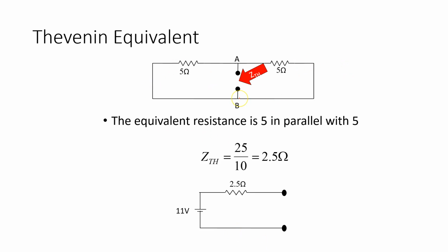If that is difficult for you to see, sometimes you look at it and you think that, well, these two look like they're in series. But remember, we're connecting from this point here. So if I take these 2 points A and B, and I draw a line like that, then I could say this resistor is connected from A on this side to B on this side. And this resistor is connected from A on this side also to B on this side. And I would get that. That is because I'm looking in at that center point. So this and this is the same configuration. So here I think it'll be easier for you to see that these two 5 ohm resistors are in parallel. And you could always redraw the circuits like this if it's easier for you to see.